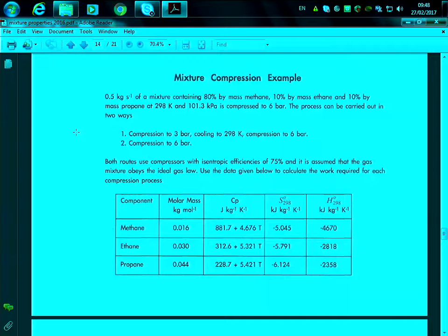When we started calculations for compressors, you remember that there was an assumption that we later fixed. Which was that assumption? It's related to entropy. In a compressor, what is the assumption that we make? Same entropy, isentropic. Okay, same entropy at the beginning and at the end. And what does that mean? What does it mean that the entropy is the same at the beginning and at the end? Delta S equals 0.